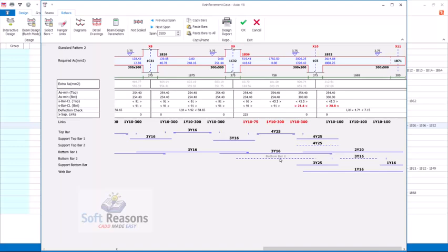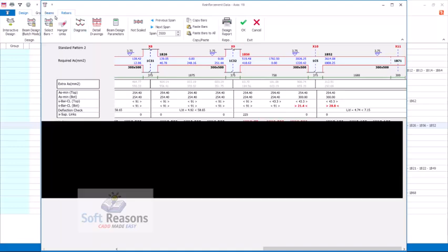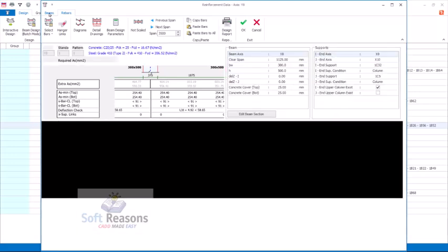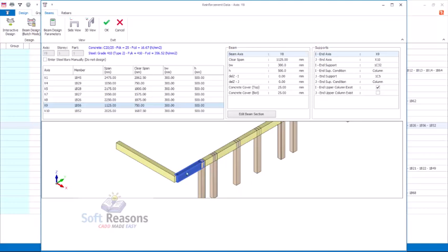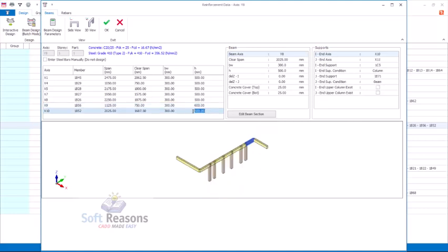All right, so what do we do at this point? You have to increase the depth of the beams. Okay, so to increase the depth of the beam, you can come over to this provision where you have beam options. Okay, so this will show you the beam systems that we have in this provision, just like this. Now we can change this to 600. All of these beams, just make them 600. Okay, make all these beams 600 depth.